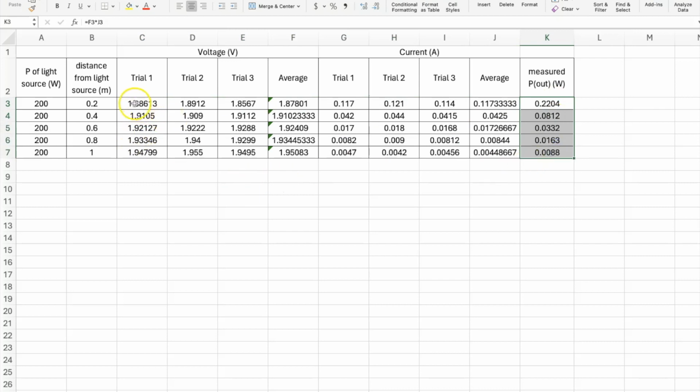That is not okay. You absolutely must, when you do a lab, show your observations. That's non-negotiable because you don't have a meter that measures power out. The way you got power out is by measuring voltage and current, so you must show that.